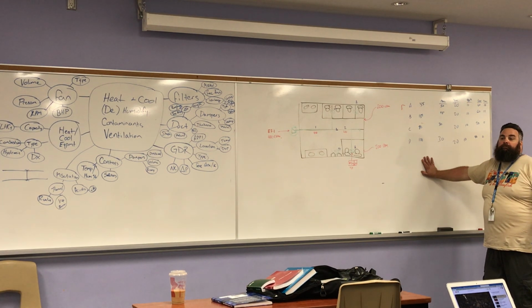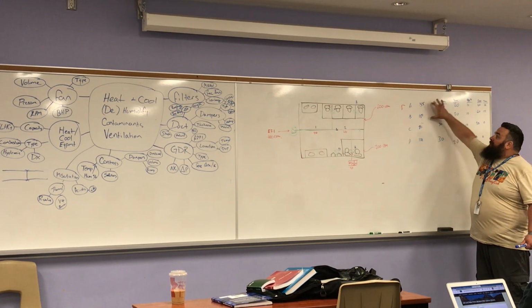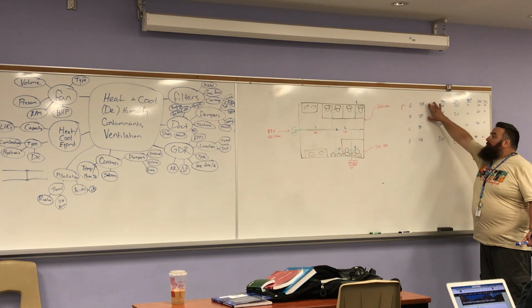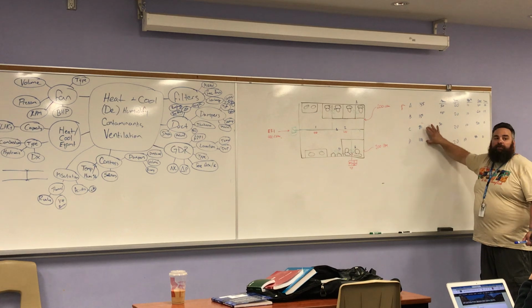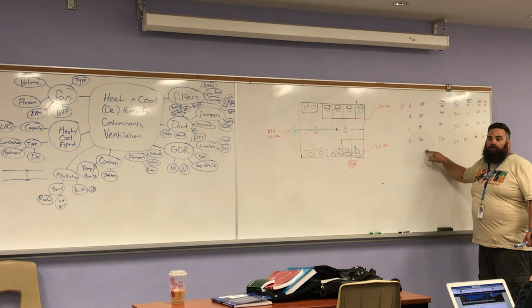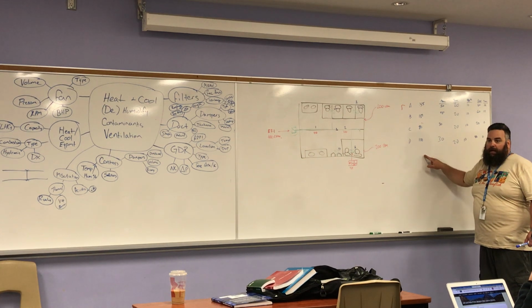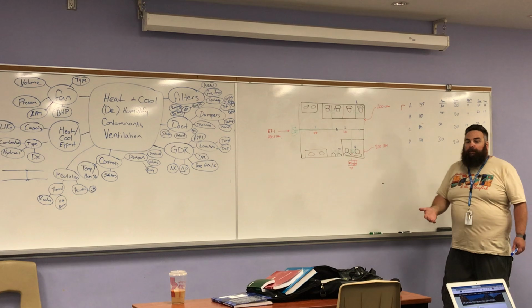The air will not move from the long one. We would have less air. Instead of the 100 we were asking for from A and B, we might get 80. And instead of the 100 we were asking from C and D, now we might get 120 out of each. It's not balancing, okay?